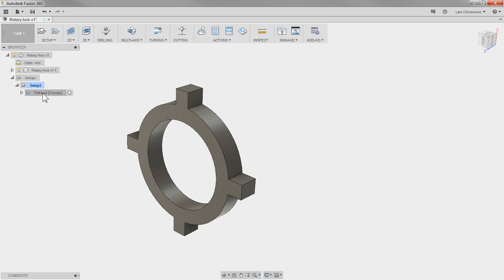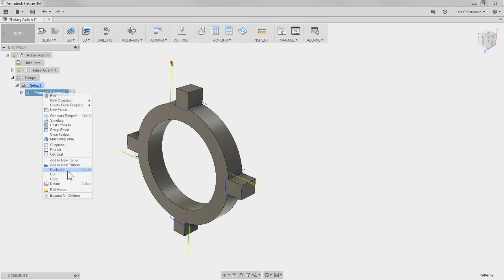So that is happening right in the right-click menu also. You can add these different patterns. So this is also great if you have a 2.5 axis toolpath. Let's say that you lay a bunch of parts out. You can just machine one contour, and then you can literally just pattern them all in all different directions. So I hope that this is helpful.